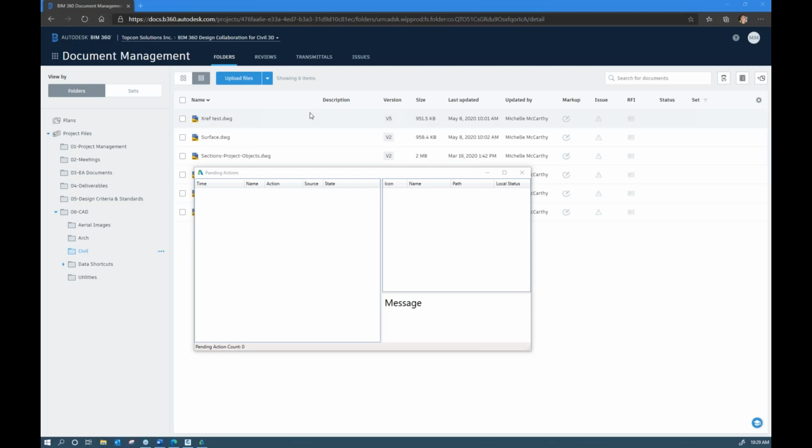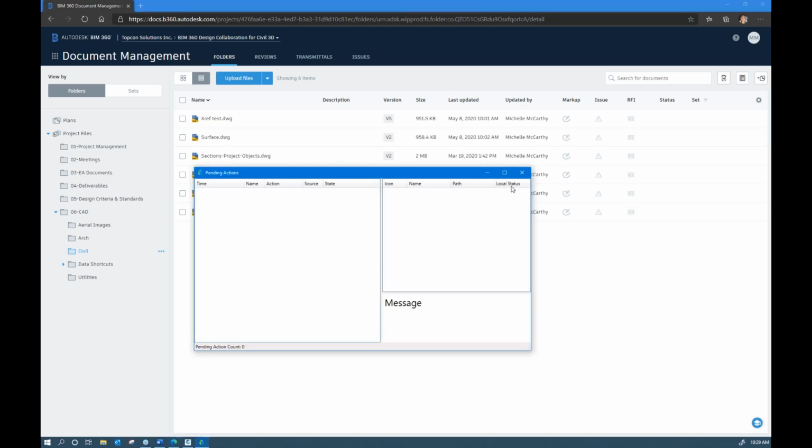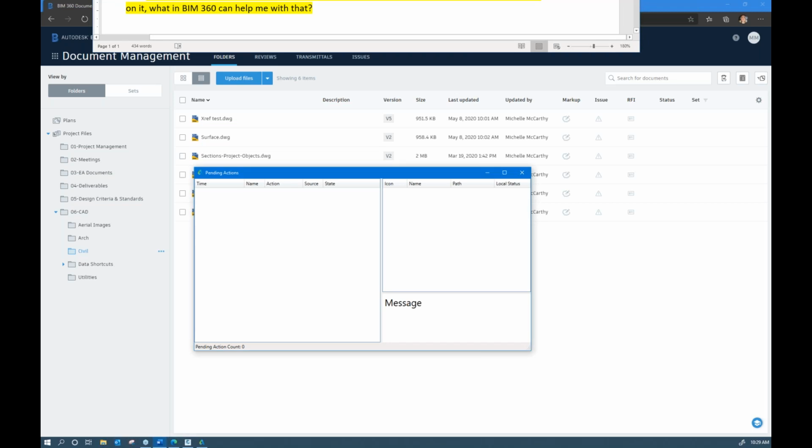Yes, so you can get around that change in versioning for the drawing each time. But to do that, you will need to download these drawings onto your computer and then take that desktop connector offline. You can do that usually on the bottom of your status bar. If you right click on it, there's a work offline option. Let's see if I can share that with you. Give me one moment.